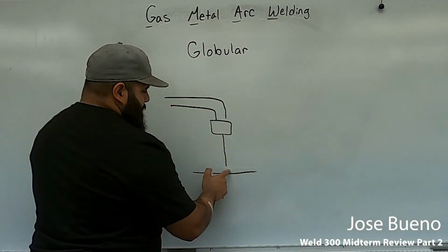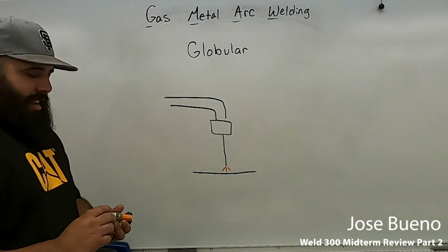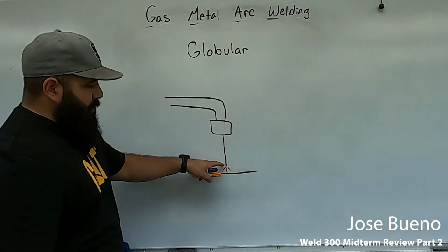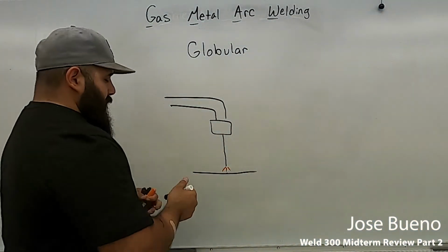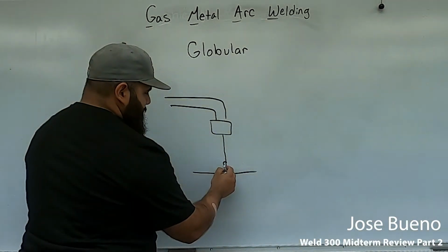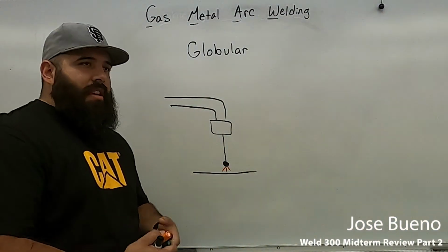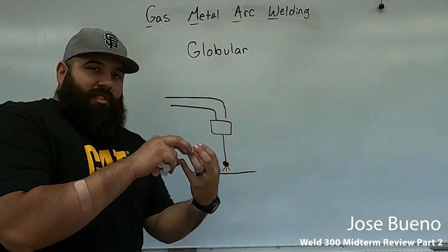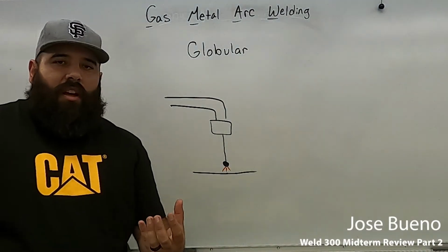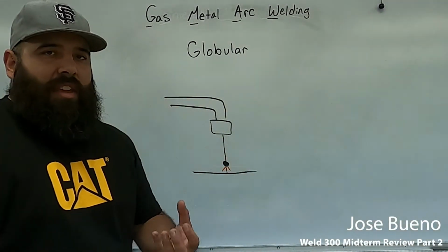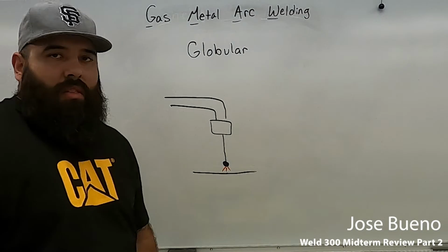Now, when the electrode heats up and melts off, the arc is established, but instead of the electrode then pushing past the arc after it cuts out, making contact again, what happens is the electrode gets pretty heated, and we have bits or sections of the electrode that melt and gather into this molten glob, and it accumulates at the very tip of the electrode until the globs essentially get too big or too heavy and separate from the electrode and then fall across the welding arc and become part of the weld.